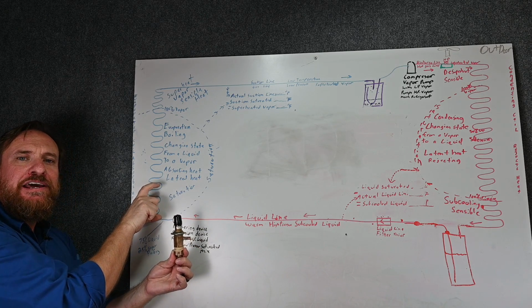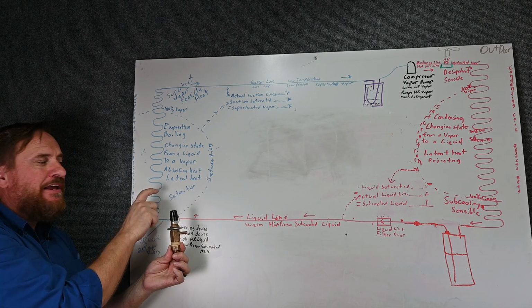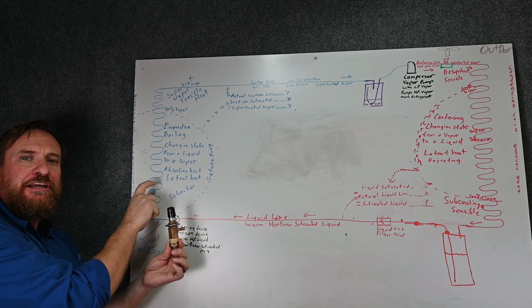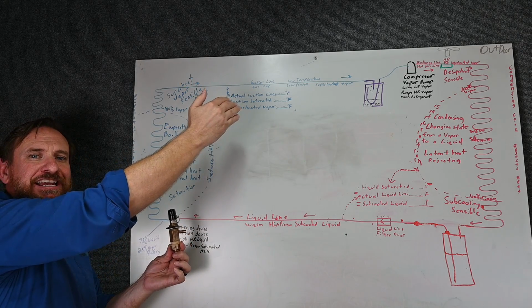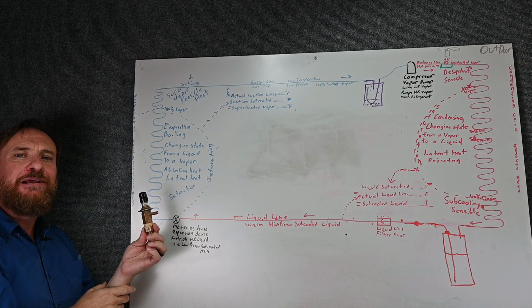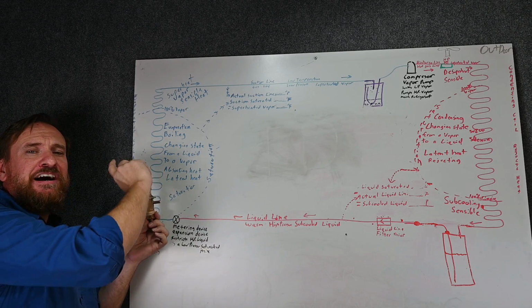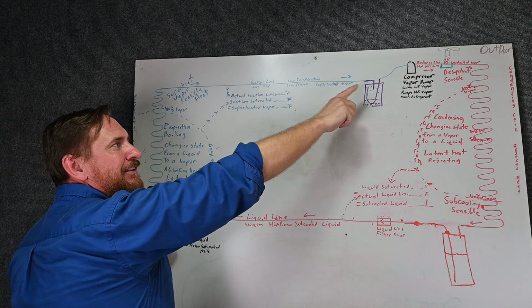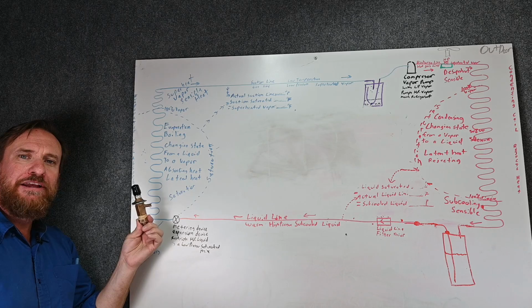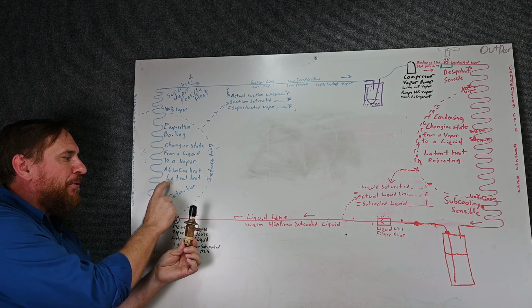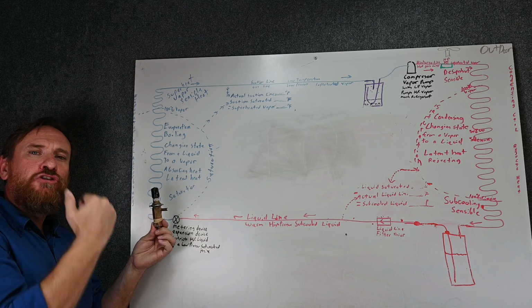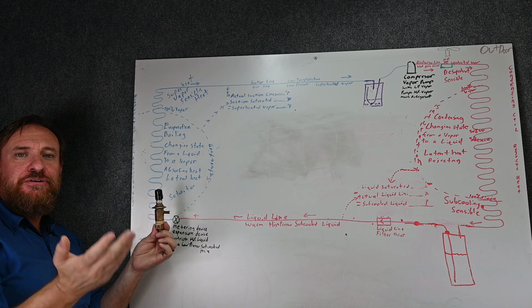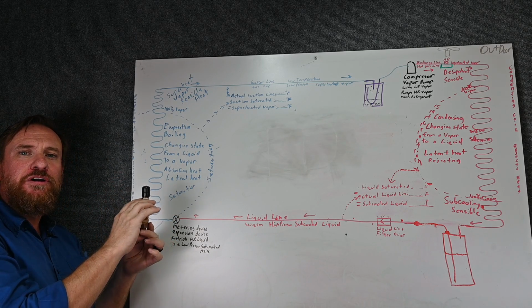Only this little bit is boiling refrigerant from a liquid to vapor. So because there's only that much boiling from a liquid to vapor, all of this is superheated vapor. A lot of sensible heat, but very little overall heat absorbed into my refrigerant. On top of that, with a high amount of superheated vapor, I end up with not as much refrigerant to cool my compressor. Now, if I'm only boiling this much refrigerant from a liquid to vapor, it's going to take a long time to cool that house back down. So on that varying load, this isn't going to work very well.